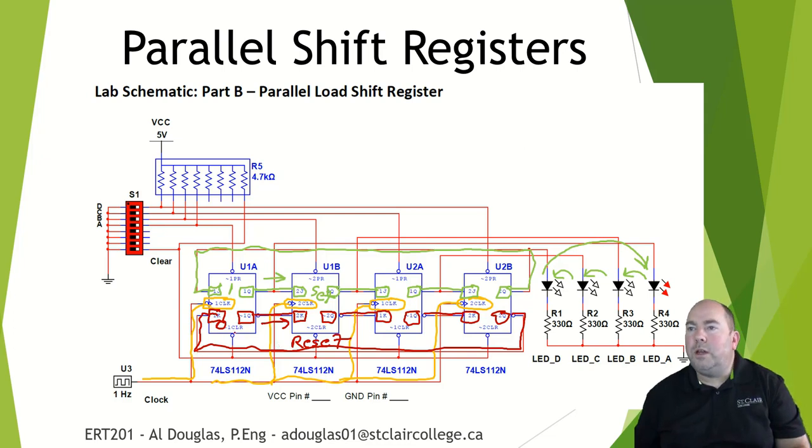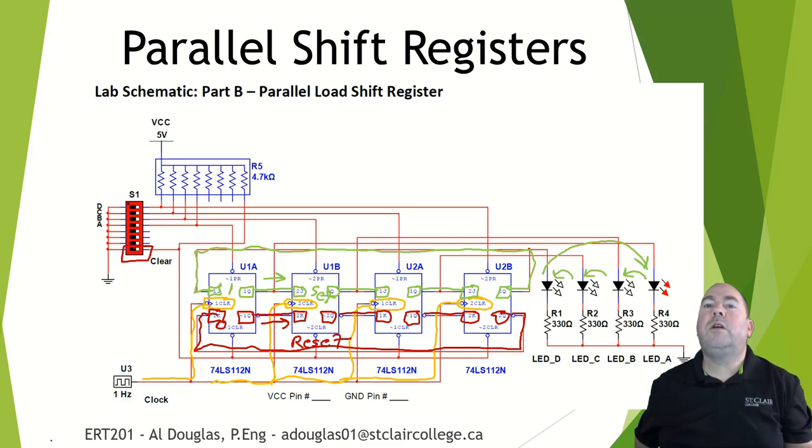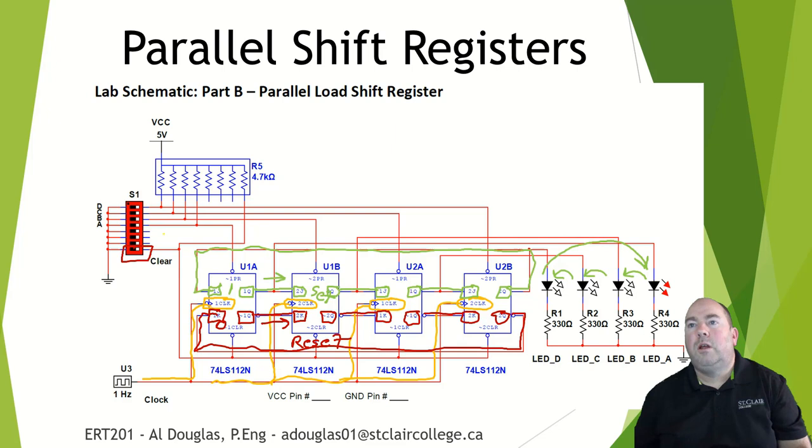You'll notice that the clears all connect together and go to a switch over here on our dip switches. Now, how do we actually get data into these? This is where we use these other switches here. The preset of each is connected to an individual switch. Each one is connected separately.